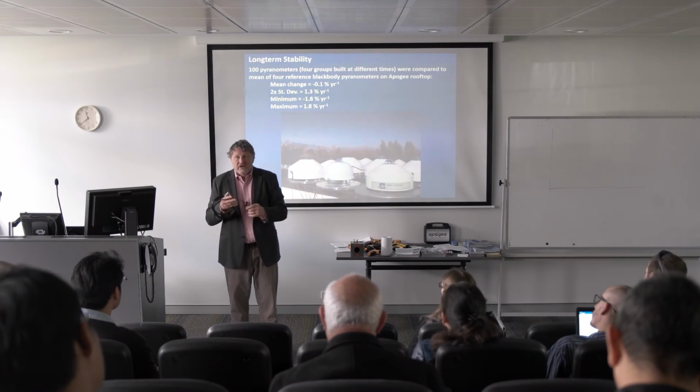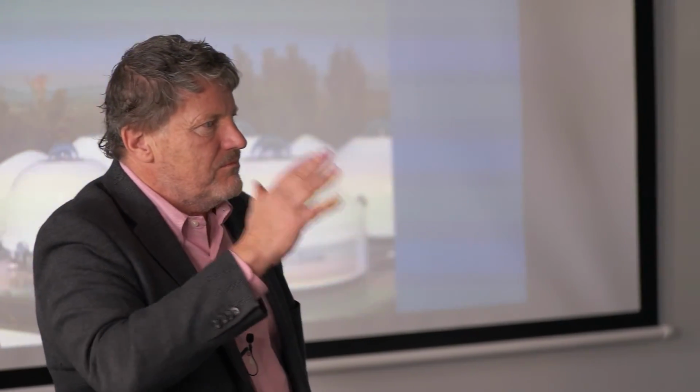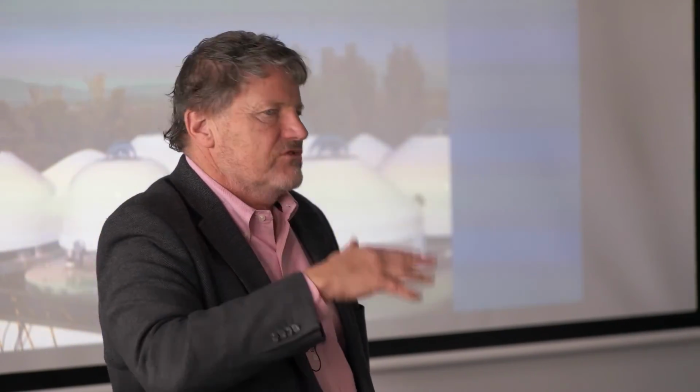You get electromagnetic noise picked up by the cable, so we shield them. That further minimizes any antenna effect of the sensor, and so the signal gets cleanly and clearly back to the detector. So shielded, twisted pair cable is the highest quality cable you can get to get the signal back to the detector.